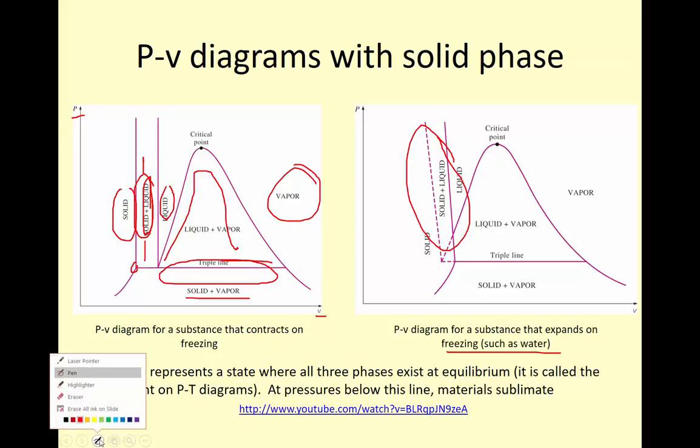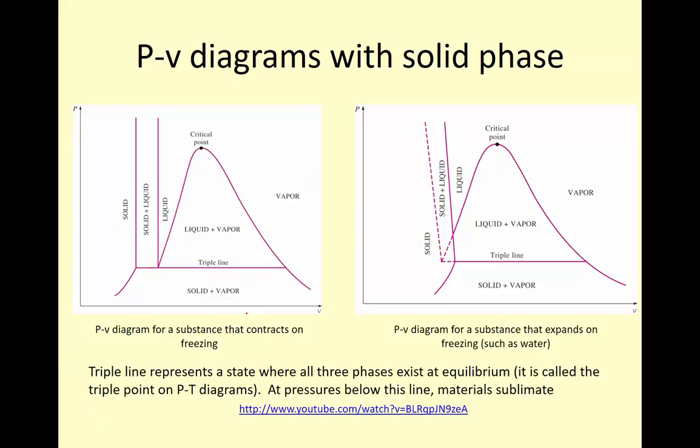So if you look at these diagrams and you're interested in knowing what process you would need to follow if you wanted to have sublimation, or if you want to avoid boiling, or whatever it might be, you could look at where you are in the space of this diagram. So let's say that you currently are in this region here, and you wanted to vaporize your substance. Well, then you would know you could hold the pressure constant, but just allow the specific volume to increase, and that would be possibly due to a temperature increase or something like that.